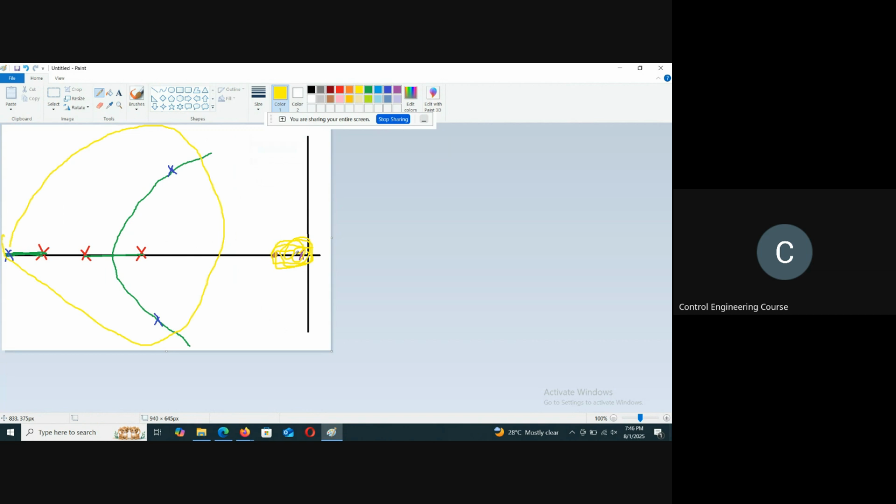You see very far away, two close enough points will appear as one, right? Yeah, that is right. So from the point of view of this faraway region, what is happening here is actually a pole zero cancellation up here, at the origin. But it's not exactly pole zero cancellation, because steady state requirements are satisfied without affecting the transient response.